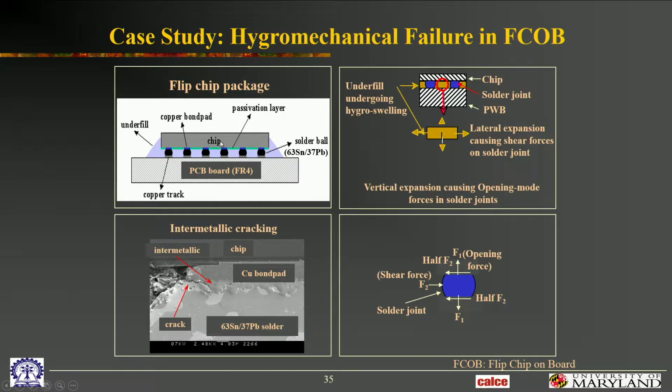This is 3 parts per million per degree C. This is 17 to 20 parts per million per degree C. The solder joints would get crushed in no time. That's why we use the underfill to reinforce the joints, right? So in this particular study, when we say we are verifying this technology, we were trying to evaluate whether the underfills would give it sufficient robustness and which underfills would work well, okay?